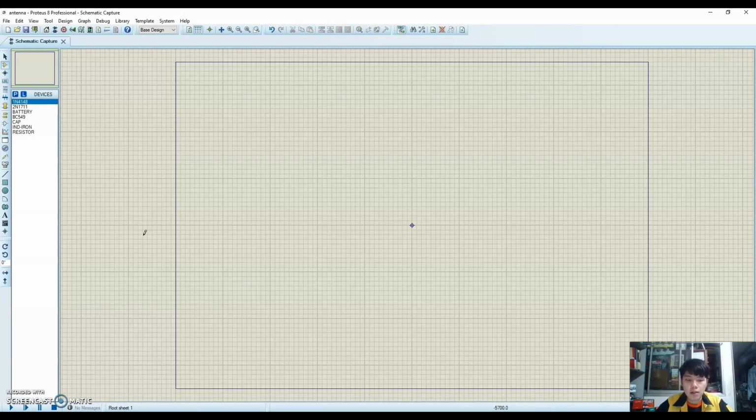Today, I will present the whole design of the receiver of our AM modulator. In this receiver design, we have to use one diode, 1N4148, and two NPN transistors, which are 2N1711 and BC549, and one battery, and the capacitors, resistors, and one inductor. So let's start to build out the receiver step by step.